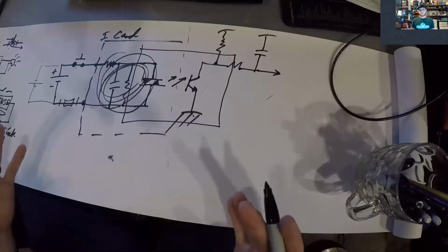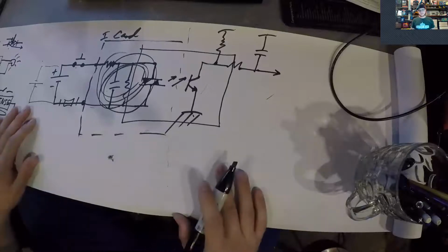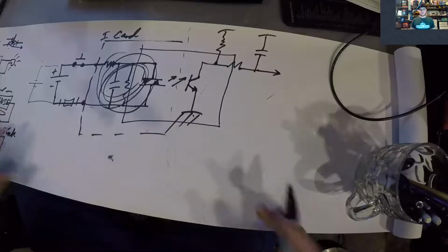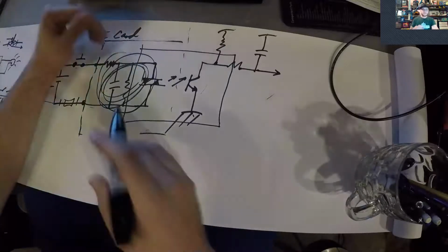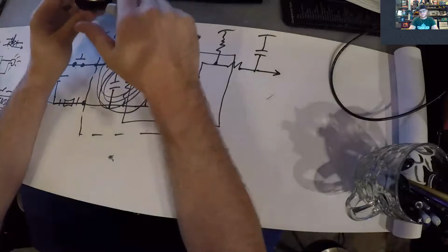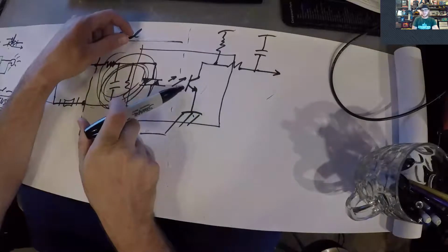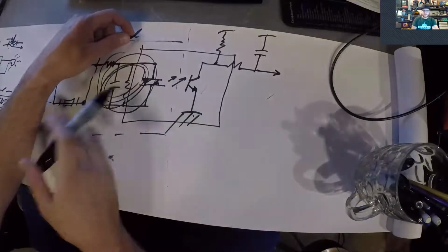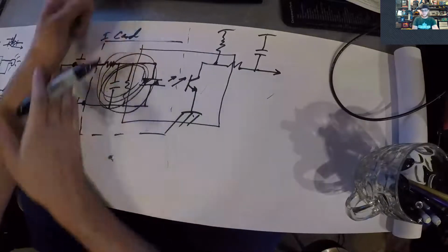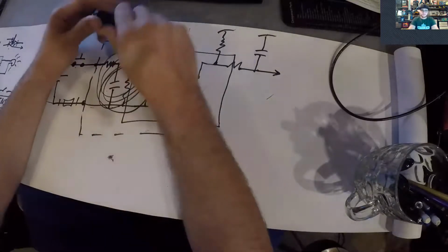Because with a conventional electromechanical relay, if you are driving along and you drive past a big enough magnet, I mean, it's not going to happen, but if a magnetron was walked past your device, it would fire that relay internally, because it's a physical system. Whereas with this, you actually need to get light in here for the sensor to read it. So I think the only way that would happen is if your component got physically damaged. And at that point, if it's broken enough for light to get in, then it's already toast anyway. So good question.